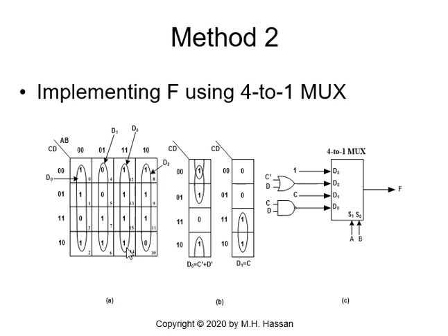And this will give me the 4-to-1 multiplexer inputs, the data lines, and we implemented the same function by using K-map. So any solution is a correct solution. We have two solutions to implement the function, either by using Boolean algebraic manipulation or by using K-map.